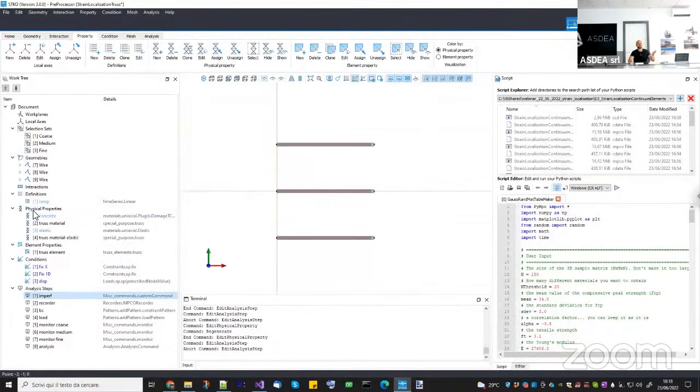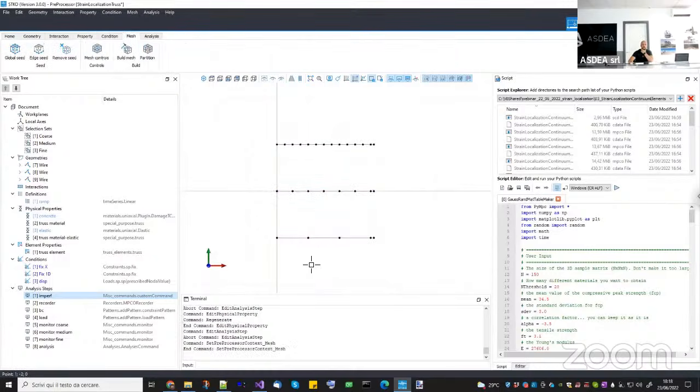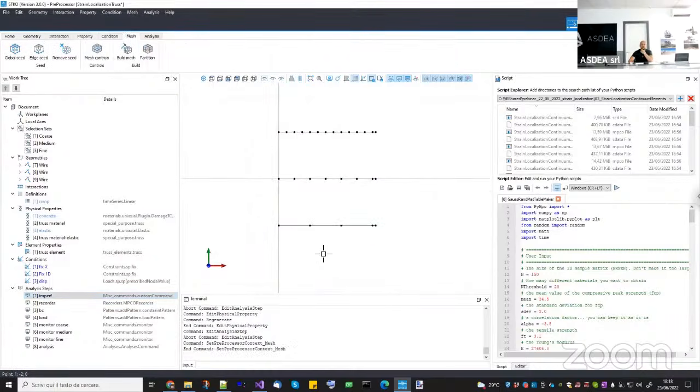So you define a stress strain model with strain softening without taking care of regularization, and you apply this one on 3 different meshes. Now, from the theory of finite elements, you know that once you refine the mesh, you converge to a unique solution. So the solution will be better, a better approximation, let's say the best approximation.